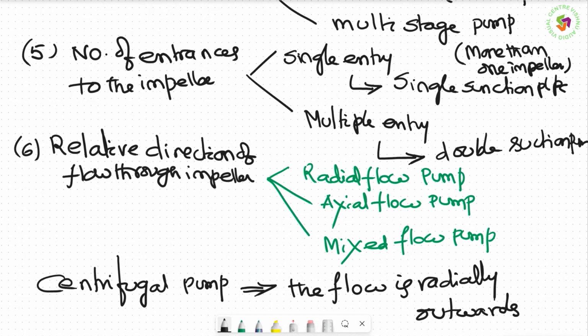In the Francis turbine, flow enters at the outer periphery and leaves at the center. Now in the centrifugal pump, water enters at the center and leaves at the outer periphery. So exactly opposite. Even the equations will be of the same nature. Whatever we have used for the Francis turbine, just the opposite of that we will use here. I will show you as we move forward into the next lecture.